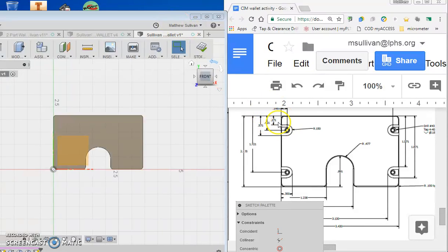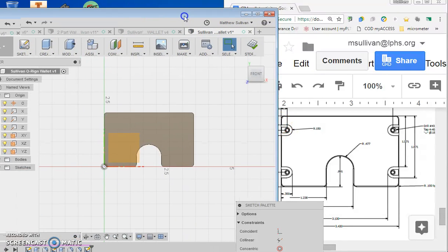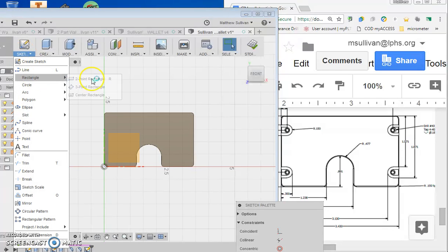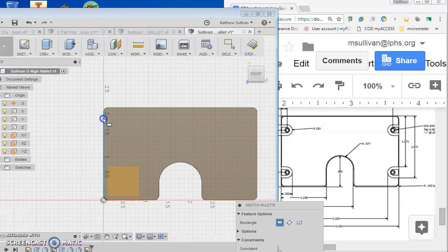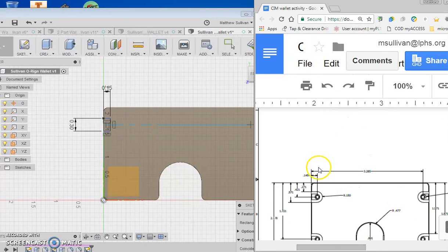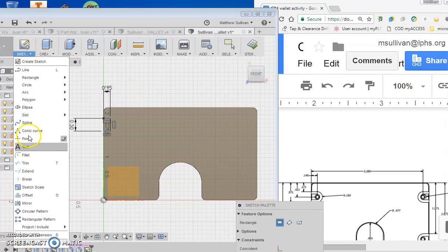So we're going to go down 0.271, and we're going to make a sketch that's 0.571. So we've already started our sketch. We have a rectangle tool, and we're going to begin sketching a rectangle. That rectangle is 0.3 going up and down. It is going to be 0.15, I believe, going over. So I just need, I can't quite see it. It's 0.145. So hit escape,